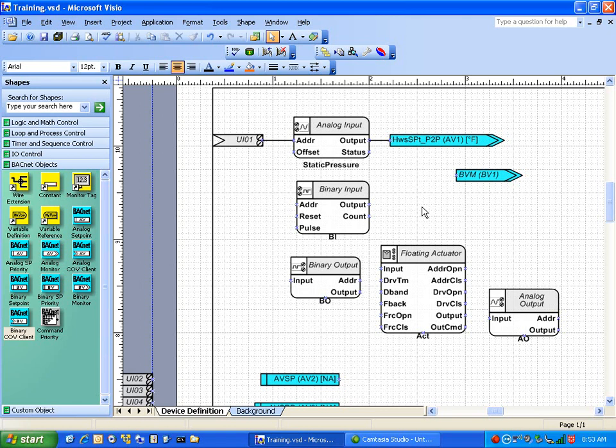However, it's a lot easier to do them down in Workplace Tech. There is a servlet, and maybe someday I'll have a little class on servlets, but there's a servlet called Admin Tool that you can add to your stations. And with that, simply what I do when I'm doing an entire job, I don't worry about individually going into all those BACnet objects and manually turning them on and setting a COV. I use this admin tool, and in one command, I can take every BACnet object and turn Use COV to true. And poof, I'm 100% set up on the entire job for COV to work.